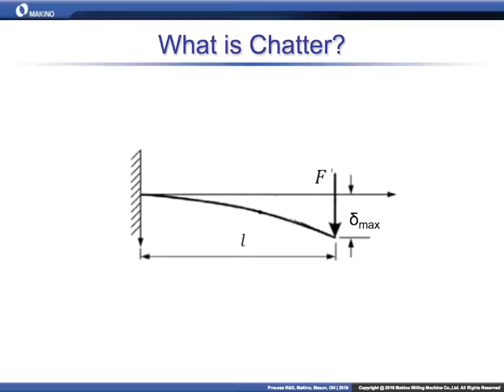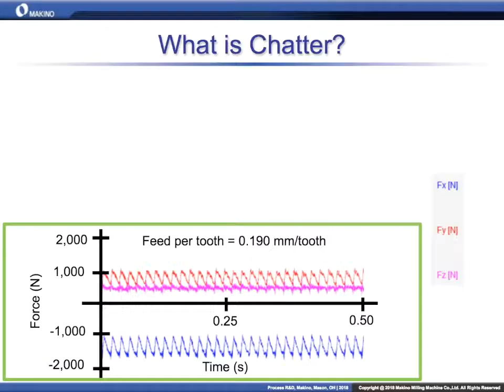Yes. And so we go to our next graphic here. You have another dynamometer, another force measurement. Yes. Which I think is just incredible. This x-axis you're showing me is half a second. Half a second. All of this data was gathered in half a second. And each of these humps is 1/2 of a cutter entering a workpiece. Is that right? Yes. So you were saying, like 30 different tooth passages on this. And in this case, the feed per tooth was about 0.19 millimeters, which is just under 0.008 of an inch. And so this is generating these cutting forces.